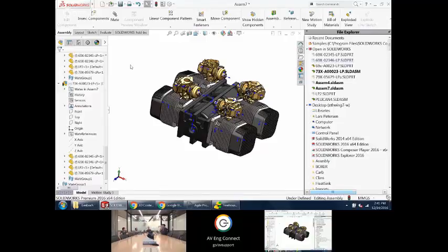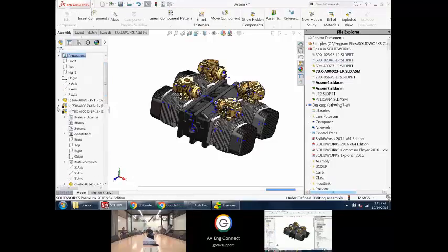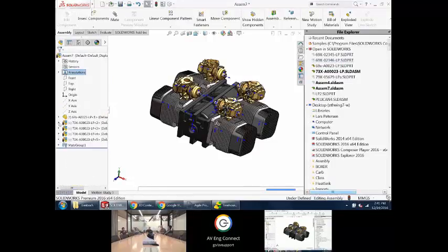Oh. So it gets really deeper than this. Okay. Yeah. You get 90% of the benefit from just doing one of them. Right. Okay. So I showed you some tricks putting mates in. Definitely that Alt key is your friend. Use that. Going window to window is a really nice trick.